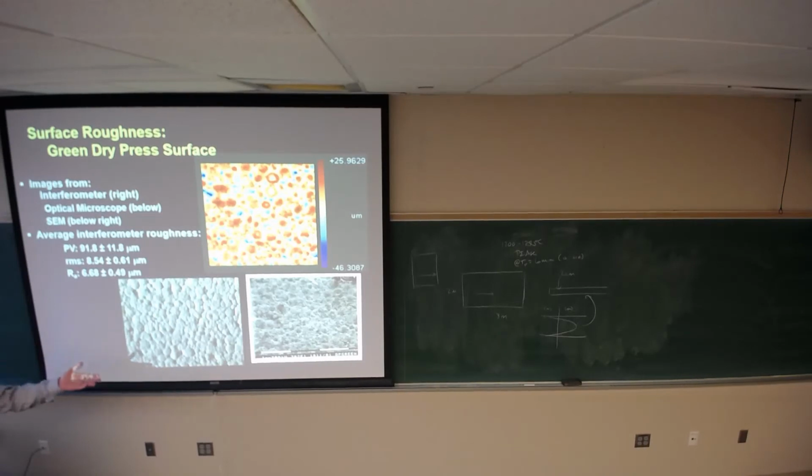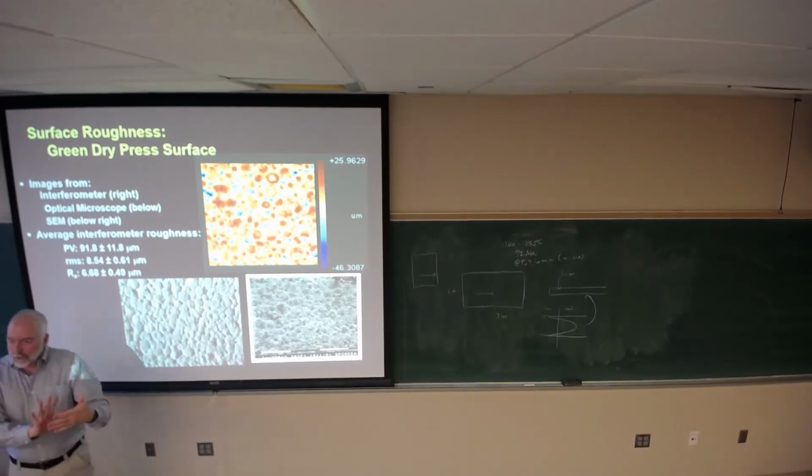Now, in tempered glass, how do I detect the stresses in glass? You know that you can do that, right? Typically, we do it optically. The easiest way is optically. You take cross poles, right? You take polarized sheets, and you cross them. And so when light comes through, it gets plane polarized one direction, and then it's 90 degrees to the plane polarization of the next, and you get opacity.